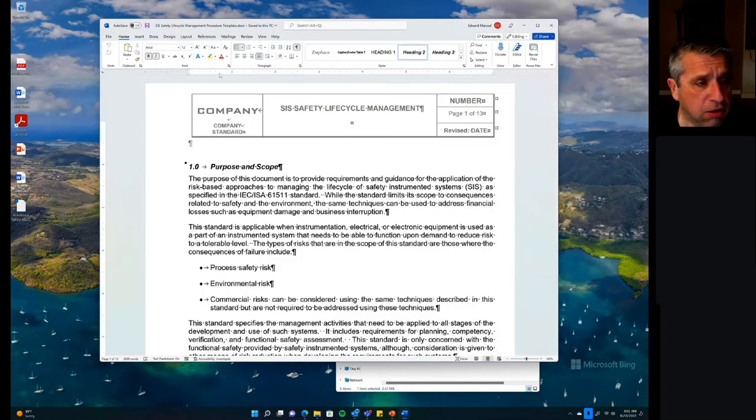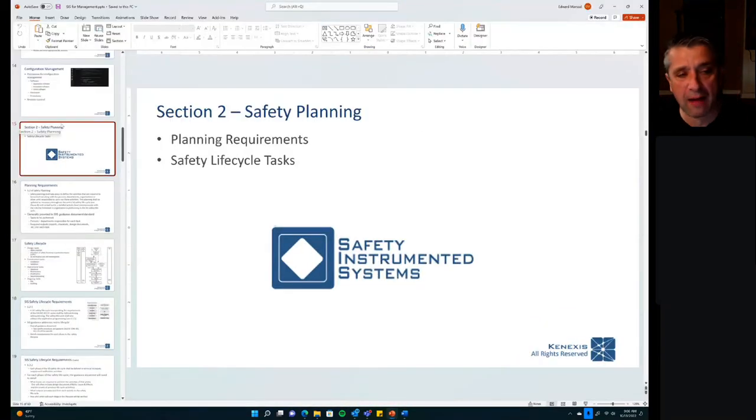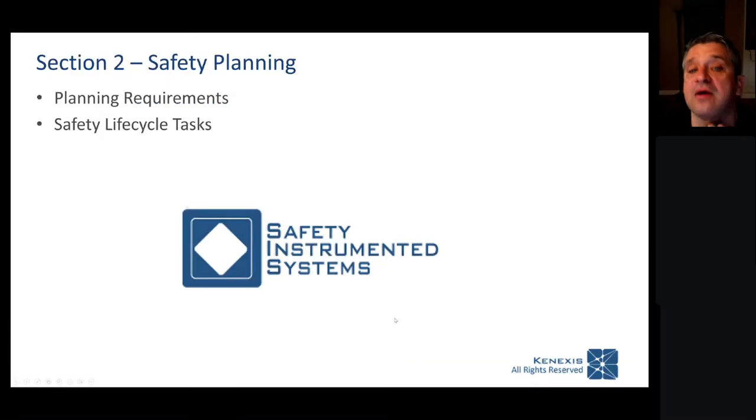Okay, let me start out by going into the PowerPoint slides. Again, this is for the overall SIS management class, but I'm only going to go over section 2 of this class, which is safety planning. In terms of safety planning, this is all going to be in clause 5 of the 61511 standard. We're going to talk a little bit about planning requirements. What do you need to plan? What do you need to think about in terms of a corporate standard, a site standard for how to implement the SIS safety lifecycle?